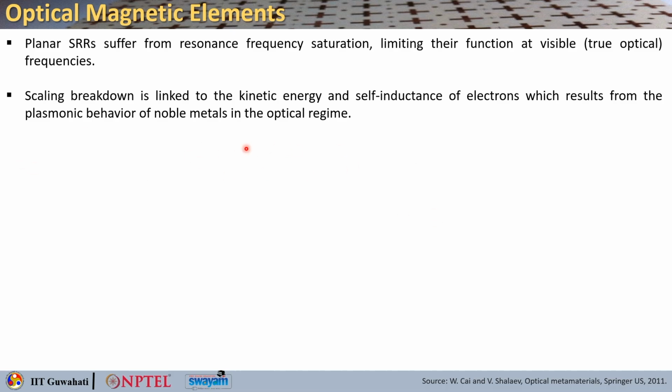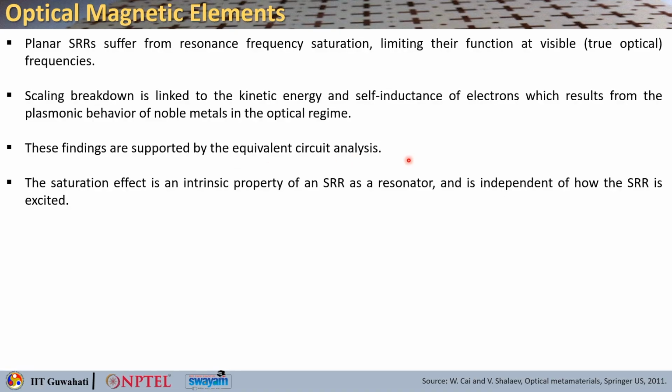Now, the scaling background of this kind of single SRR is described mainly by linking to the kinetic energy and the self inductance of electrons, which basically come from the resonance behavior of the noble metal that you are going to use in the optical frequency regime, right. So, these findings are basically supported by equivalent circuit analysis, and the saturation effect comes out to be an intrinsic property of an SRR as a resonator, and it is basically independent of how these split ring resonators are getting